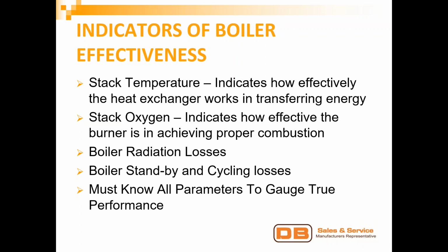Stack oxygen. A burner in its root element is really a mixing device. It mixes fuel and oxygen to give us a homogeneous mixture that is then combusted and gives us a flame and allows the energy to release from the fuel. But a burner is really a mixing device. And there's a burner on every gas-fired boiler. The stack oxygen indicates how effective that burner is in achieving proper combustion. The higher the amount of stack oxygen, the less efficient that burner is actually operating.